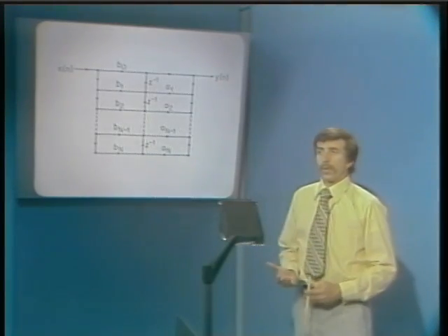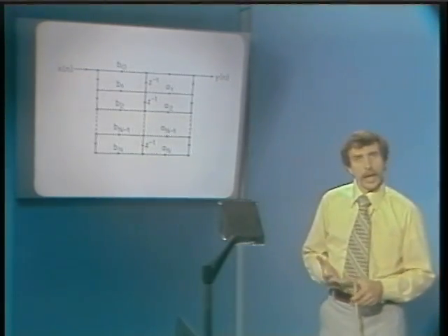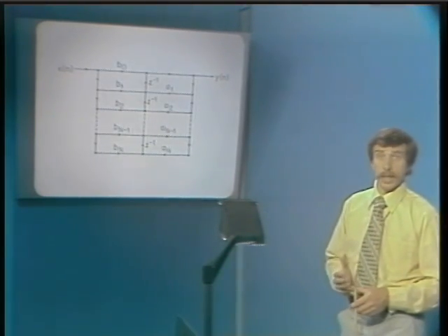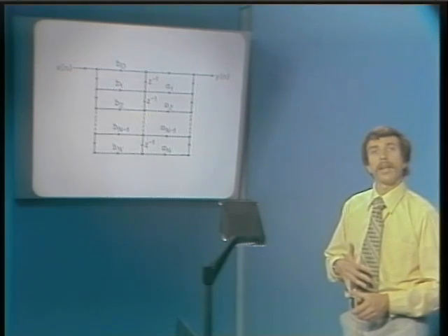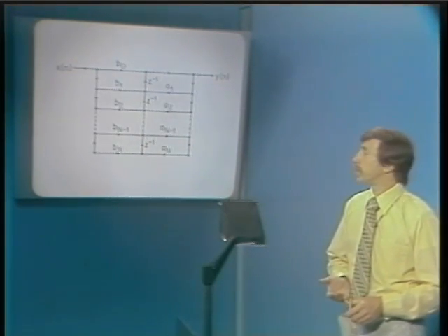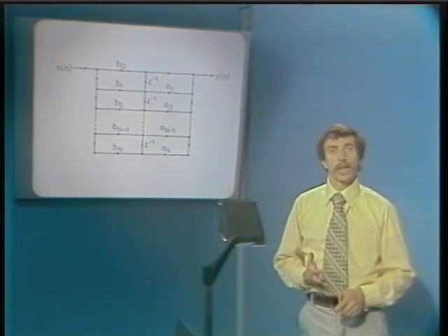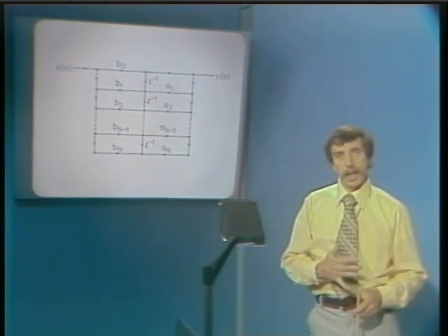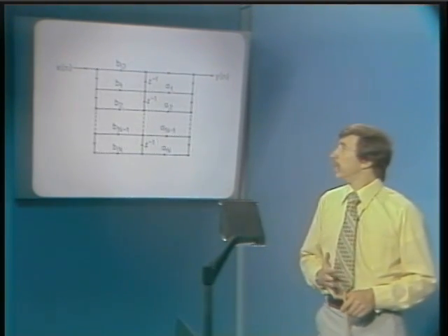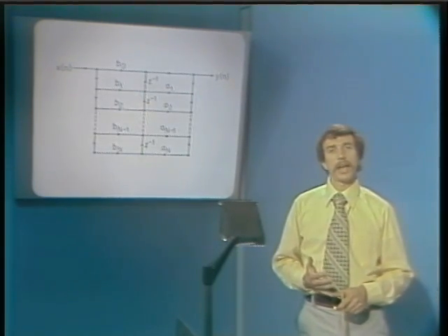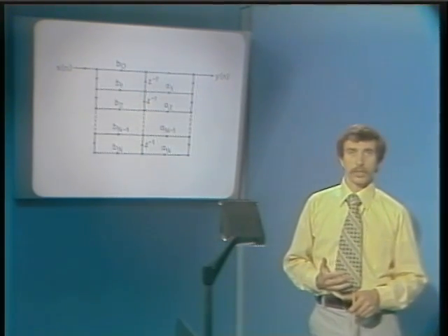All right, so some structures are canonic form and some aren't. The first one, in fact, that we developed wasn't canonic form in the sense that it had more delays than were absolutely necessary. The last two structures that we've shown are canonic form structures in that they have the minimum number of delays. All of these structures are referred to as direct form structures.